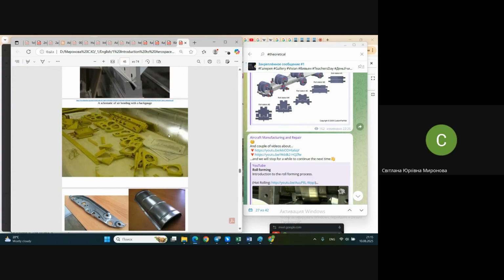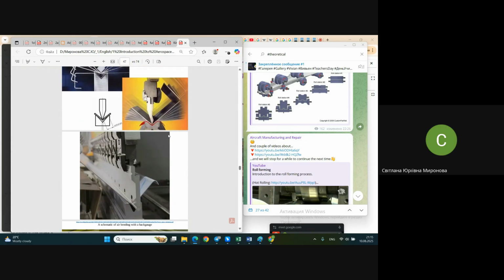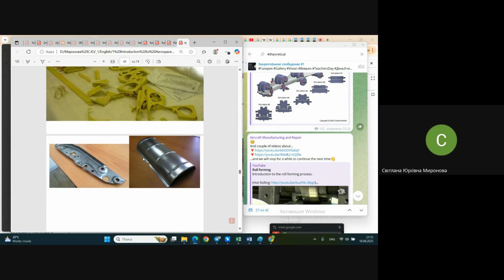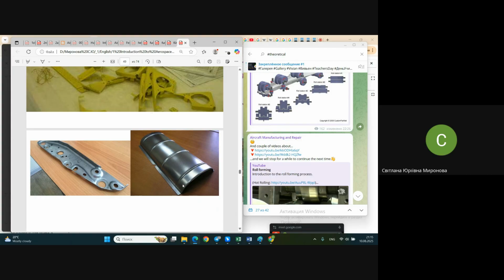What forming, the bending, once again we see forming, maybe of complex shape like this. It's not drawing because it's not a closed shape, it's not closed in perimeter, and it has no squeezing of material through the gap, let's say, between punch and die block.